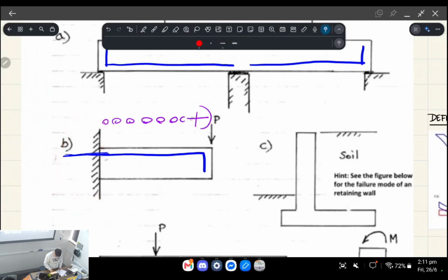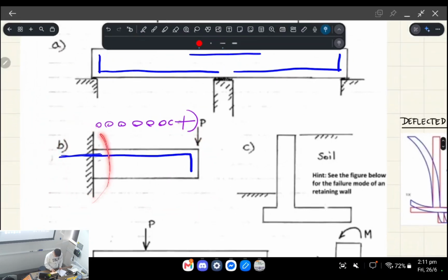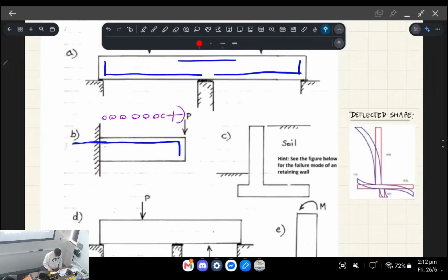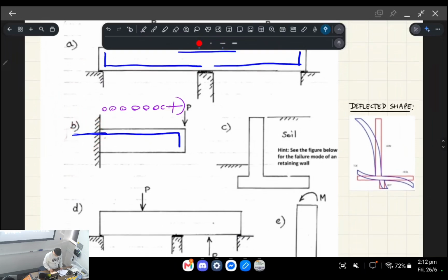We normally think of a problem as ending when you see the support, but essentially your bar should start in the wall. Imagine this is a wall, and then this is like a cantilever beam or slab coming off of it. You need a starter bar in the wall so that it can behave together with the beam. So it actually starts in the wall.